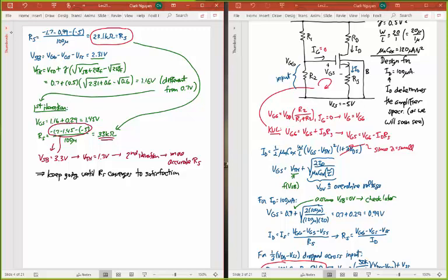It'll keep converging, but at some point you're going to be satisfied. And for me, I'll probably be satisfied with this 33 kiloohms. I won't have exactly 100 microamperes, but I'll have something close enough to get my amplifier to work the way that it needs to. And you're going to learn in a bit what you need to get your amplifier to work like.